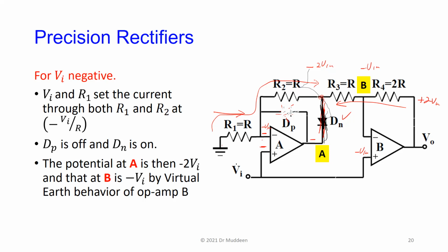So here, remember Vin is negative. So I have minus Vin here, right? Remember the current flow into the op-amp is 0. So we have a current flowing here, that is minus Vin over R, nothing is flowing into the op amp, so that current is now going this way. So therefore, I'm going to get another Vn being dropped across here.